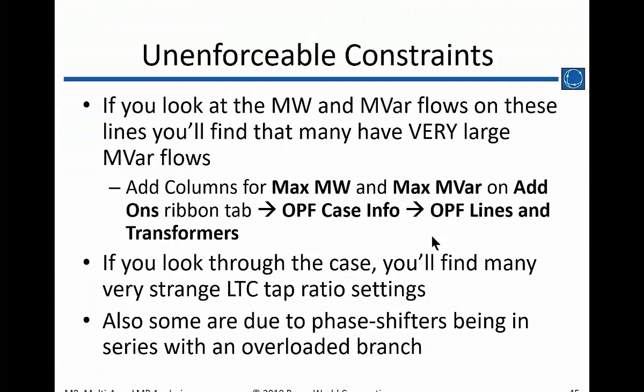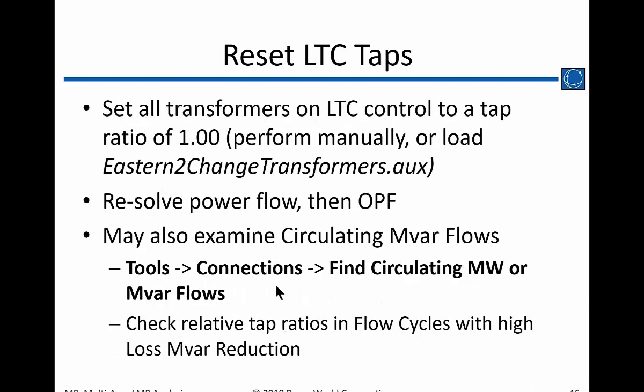Yeah, there was a reactive power issue there. But in this particular example that's described on the slide, there are some tap ratios that are out of whack. If they're all initialized at a value of 1 and then resolved, then the reactive power flows drop quite a bit. The power factors go up on a lot of those elements, and you don't have overloads. Again, if you use the DC power flow, then this goes away because it doesn't worry about trying to enforce voltage at that point.